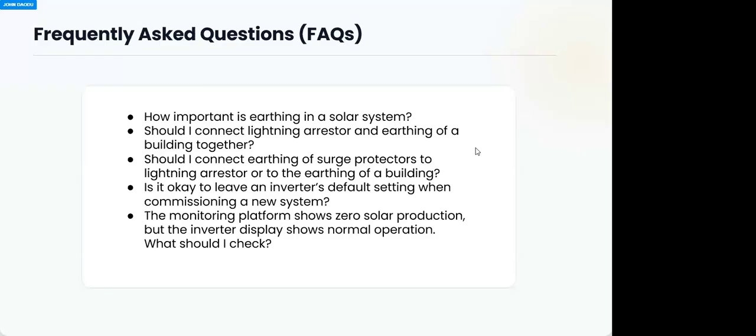So it is you that will set both charging current and voltage, because the charge controller does not even know how many batteries you want to connect. It's you that will say, okay, I'm connecting 2 strings, and these 2 strings need 40 amps. This charge controller can deliver 100 amps, so let me set it to 40 amps that is required by the 2 strings.